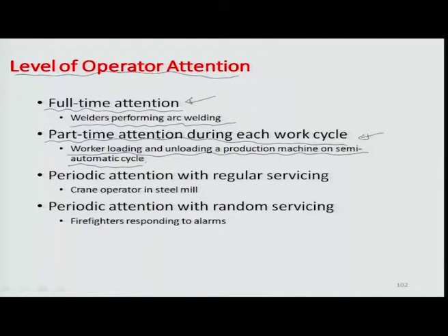There can be other cases where the level of attention could be periodic with regular servicing. For example, when we operate a crane in a steel mill, you need to be very careful, probably at every shift end, about seeing all the joints and all the cables and inspecting the different components associated with the crane for snap, breakage and also fatigue, so that you do not have any accidents in the next cycle of operation.